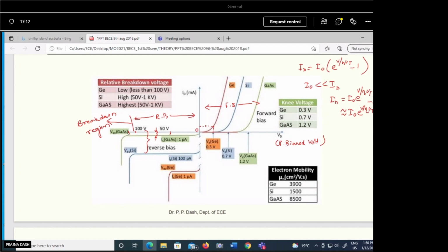should be used under the region, that means the diode should not enter into your breakdown region. So there should be a limitation. That limitation is usually given by the manufacturer, which is called the peak inverse voltage, or the PIV rating of the diode.